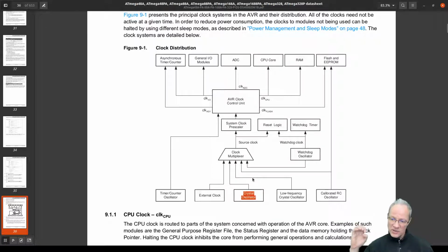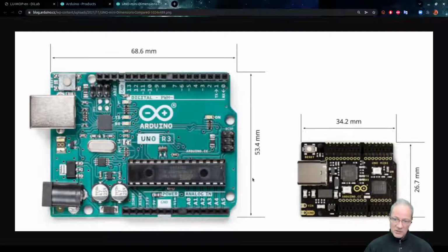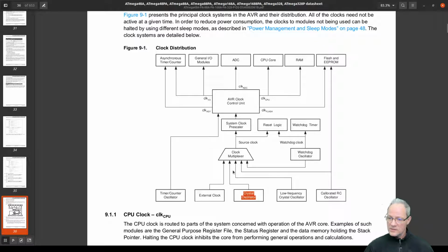So you can attach a crystal to this chip, and most likely it has it somewhere. Yeah, right here. That's a little device. It's called a crystal here. So that will provide a stable clock of probably 32 kilohertz to this system, and you can use that clock to actually configure the internal clock that runs at much higher frequencies to calibrate it.